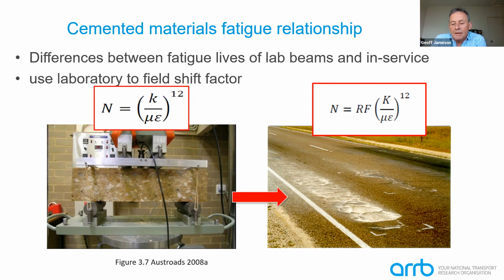In terms of the size of the cracking there, we don't have any firm data, but my belief is that the stronger the cemented layer and the thicker it is, the bigger the blocks. If you have thinner layers and less strong materials, you'll get smaller blocks developing with time. So the nature of that cracking is of interest to us.